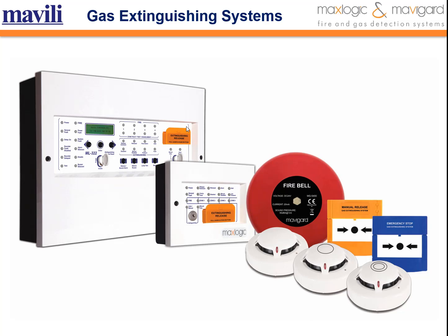All extinguishing states such as pre-activation status, activation status, extinguishing delay status, release status, post-extinguishing status, and unexpected release status are defined on our panel. And also, as I told you, we have an extinguishing status indicator unit, as you can see in this picture. Our status indicator unit allows you to move the indicators and controls on the fire extinguishing panel away from the area where the panel is located.